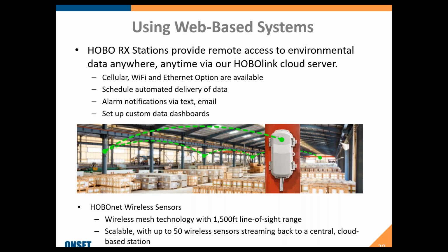We've recently come out with HoboNet sensors. So these HoboNet wireless sensors use a mesh technology. So you get about 1,500 feet clear line of sight, very strong signal. Indoors, it'll be less if there's walls. I've seen it personally on sites go 300-400 feet through walls, through metal racks, no issue at all.